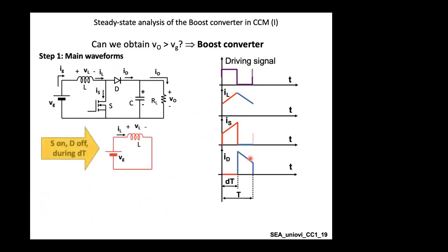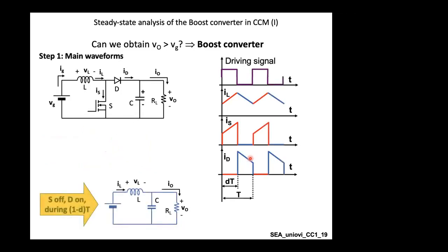Again, this will be repeated when the switch is turned on and then turned off. And if you remember, this is typically the same procedure as we did for our buck converter. Now, you can apply Faraday's law to determine the current in terms of voltage and time, knowing that V equals L dI by dt. So you can use this in order to make this equation.